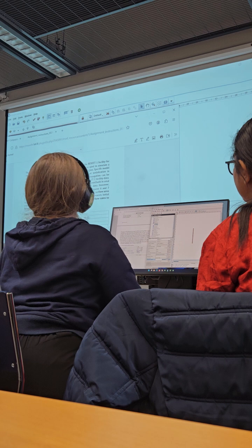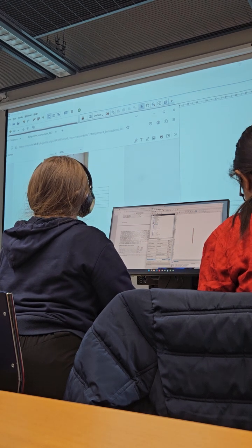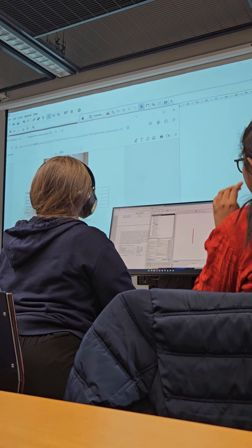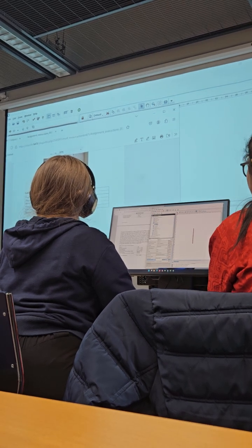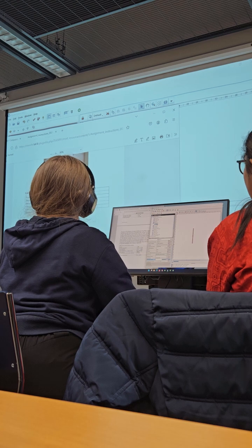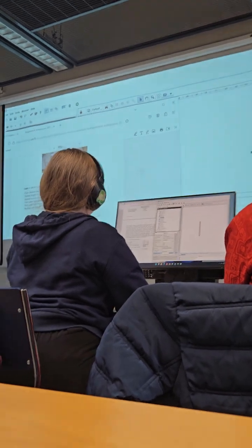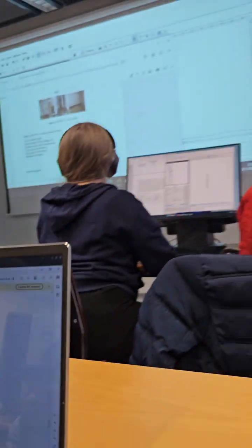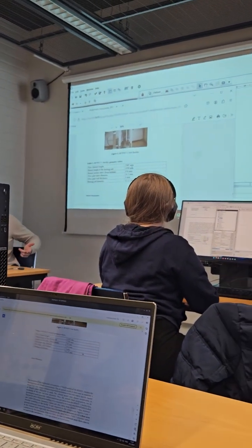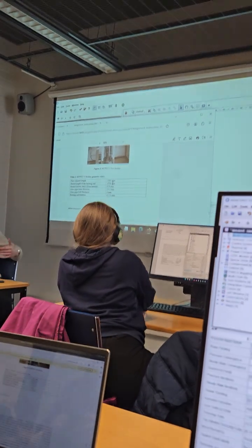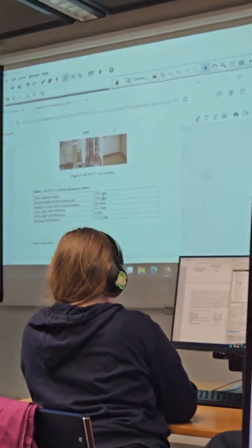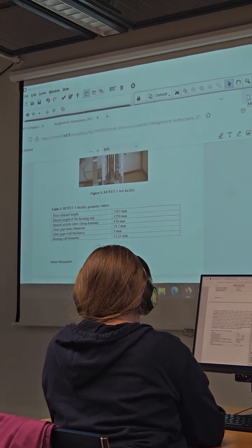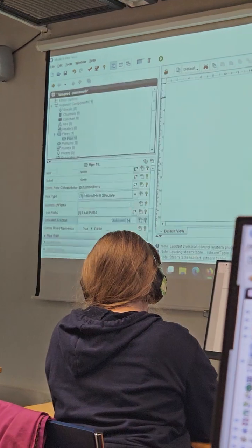So based on the parameters in the table here, the length of the glass tube is 2000 and something. The heated length of the heating rod is 1550. So we just need to calculate the fraction of the heating rod to the pipe by the length. So the difference. Since it is the unheated fraction, it is just 2185 minus 1550 divided by the total length of the pipe, and it is equal to 0.29.